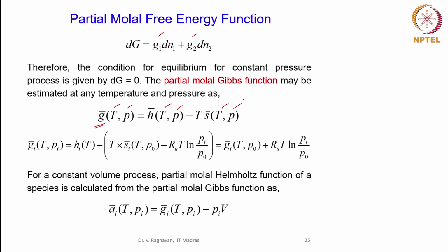Now, let us try to do this for a given species, then we can apply the mixing rule. So, take the ith species which is at temperature T and its partial pressure is Pi. Okay, the ith species has a partial pressure of Pi, that is Xi into P. So, the enthalpy of the species is Hi of T, which is nothing but the formation enthalpy HFi at 298 Kelvin plus delta Hi at T. Okay, that is the sensible enthalpy. So, that we can calculate, and you know how to calculate this. So, Hi of T will be the enthalpy of the ith species at the given temperature.